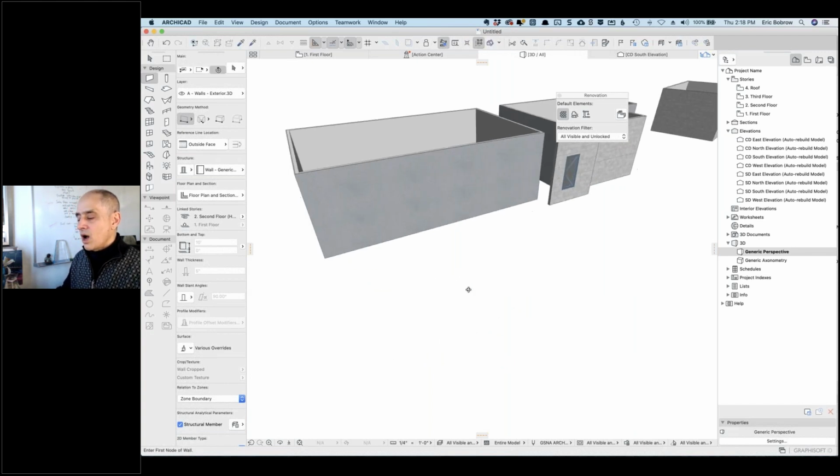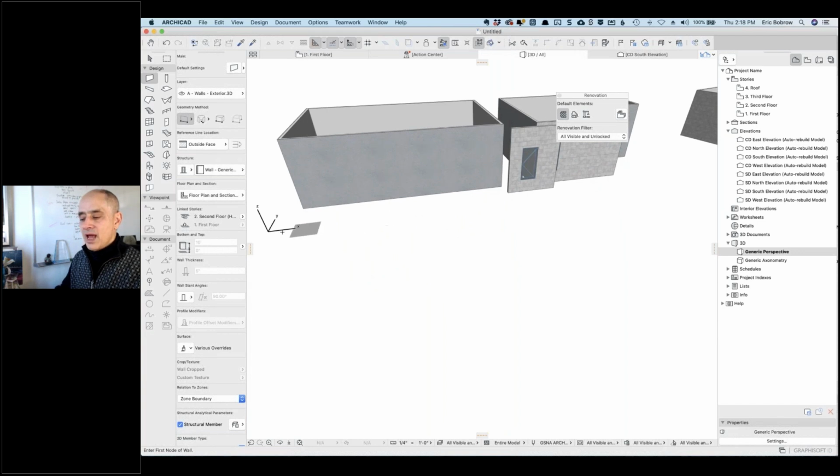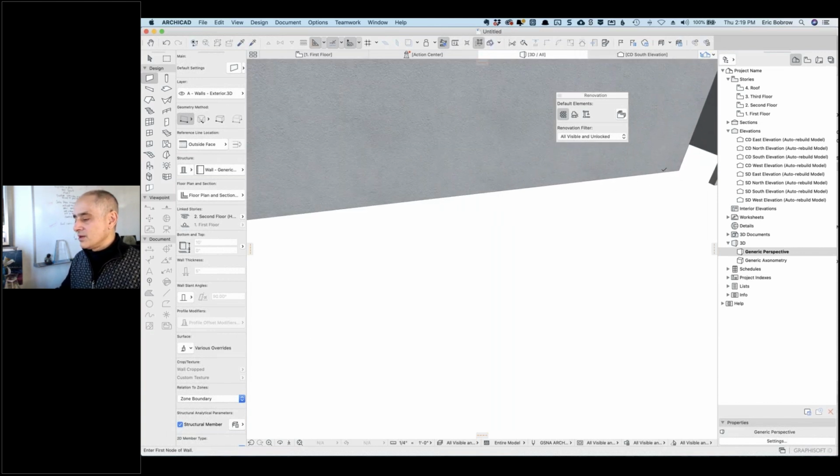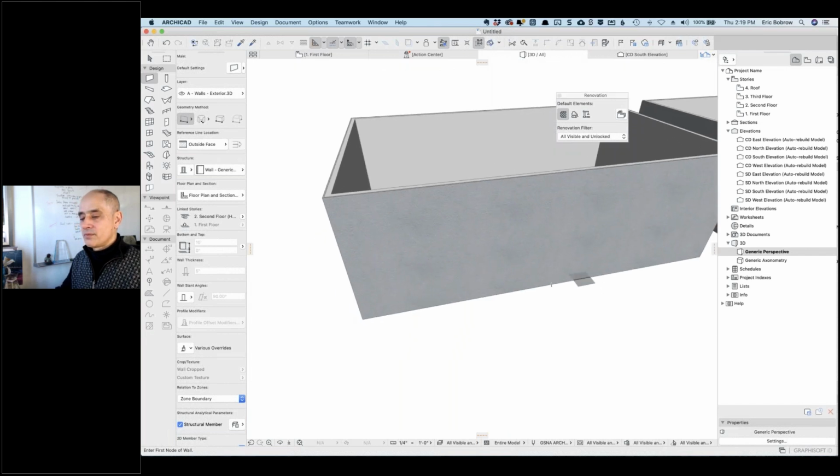All right, so now I'm looking at this building and the origin point is, you know, just a nuisance, right? I can't hide it. They used to have a little option down here that would hide that origin point. I don't know of a way to turn it off, but you can just use the set origin, move it off screen here, and now, you know, it won't be in your way. So hopefully that's helpful for you, Todd.